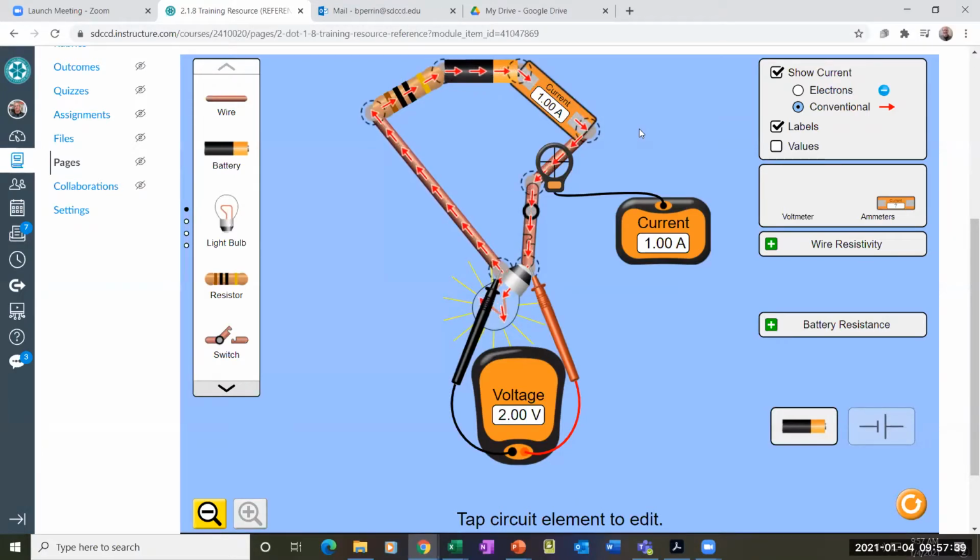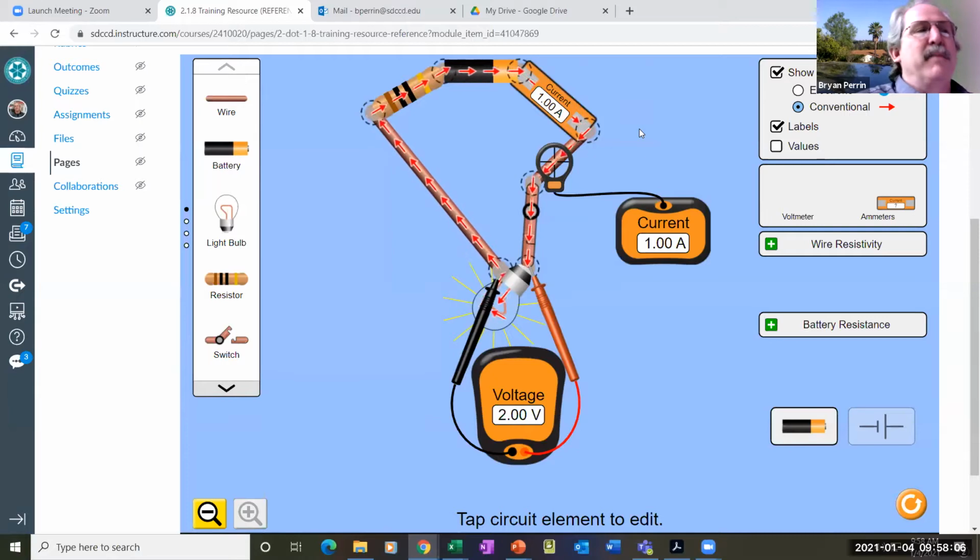So when you were talking about the injectors and not taking it apart to measure resistance, in my mind I was thinking that you have to take it apart in order to measure amperage, but you're saying by using this different tool, that's why you don't have to take it apart. Correct. Otherwise you would, and there would be no advantage of measuring amperage over taking it apart and measuring resistance. Right, and I might blow the $20 or $30 worth of fuses in my meter.